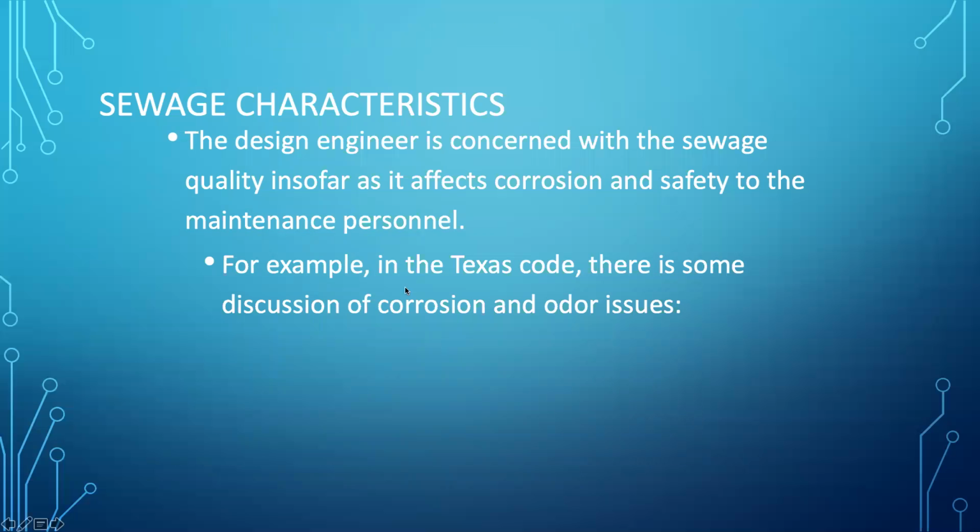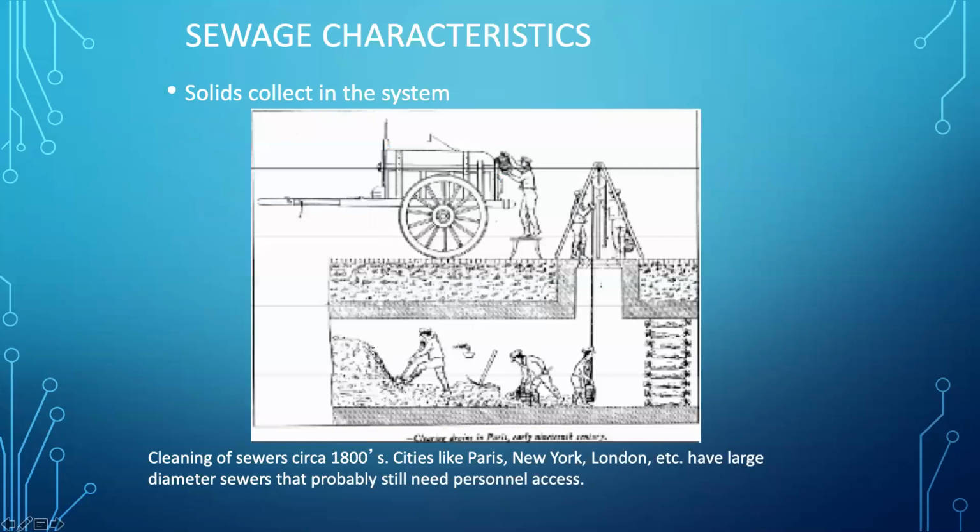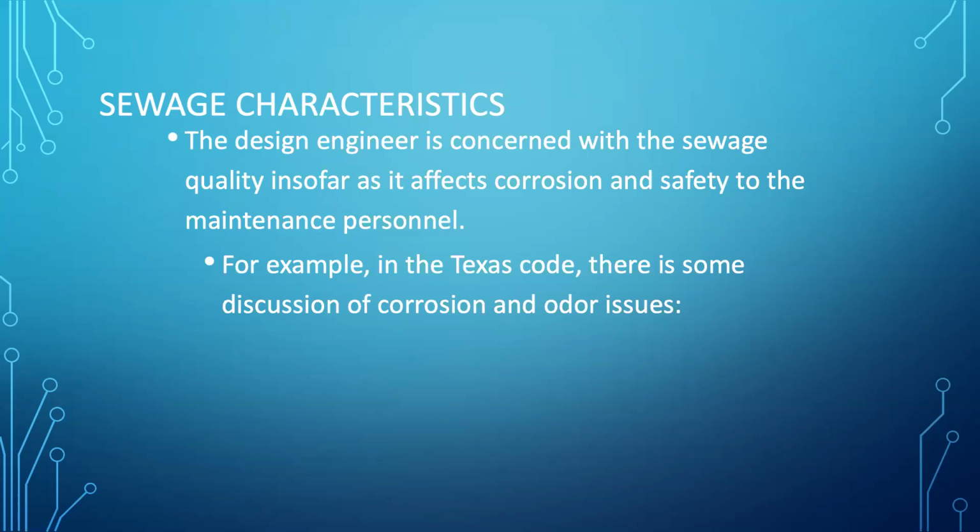And ironically, the corrosion doesn't occur necessarily at the top of the pipe, but it occurs somewhere on the haunching because the sewage is high in sulfur reducing compounds, and so it essentially makes the sulfuric acid, and that's in the air phase, and that starts to work away on the cementitious material in the pipes that support it, and over time you lose both the bottom of the pipe and the top of the pipe, and these things fail fairly catastrophically. It's not common, but it's common enough that we worry about it.